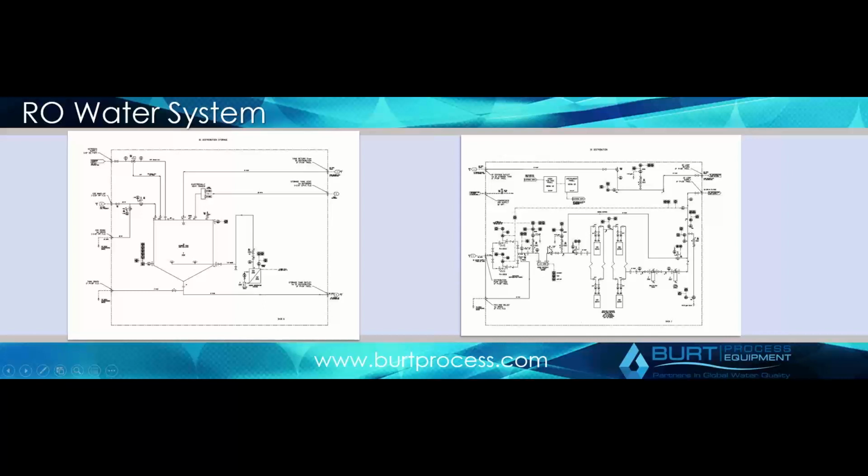You have your 254 nanometer UV here for ozone and bacteria, your DI monitoring the resistivity for exhaustion, and then your two sets of final filters here as well. So even though this is making a very high water quality, it shows that all systems, to some degree or another, have these integral components to come up with a proper design for your high purity water system.